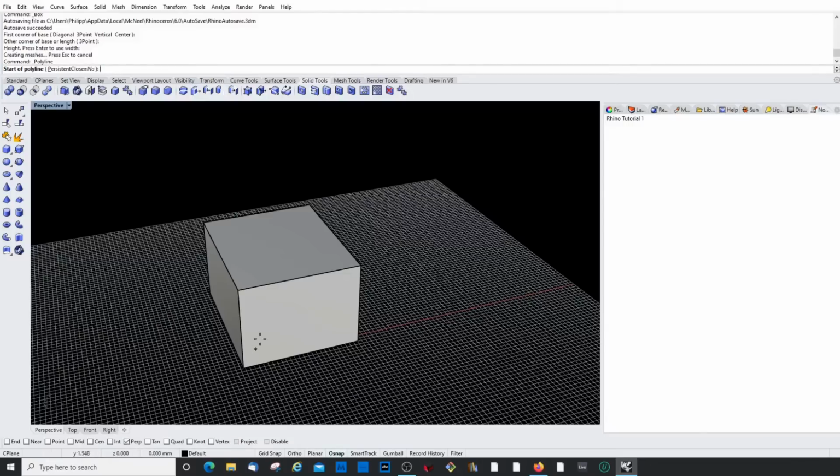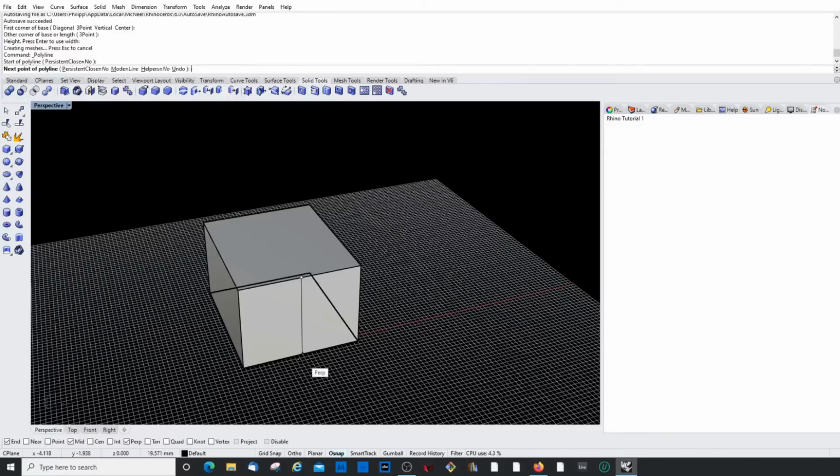Then perpendicular would mean if I started a line here in the middle, then I could snap it to anything which is perpendicular to that curve, to my line. Tangent object snaps, I can explain in another video. Project, I will explain later also. And here you can disable the whole thing. For example, if you have certain things on, and these are the ones you're working with, and you don't want to go through and turn them all off and on, you can do this here.